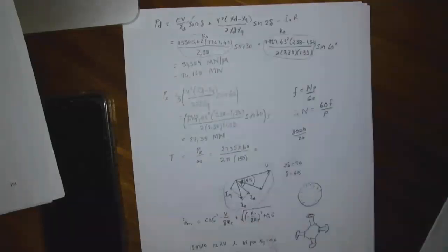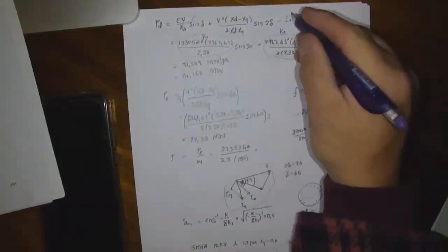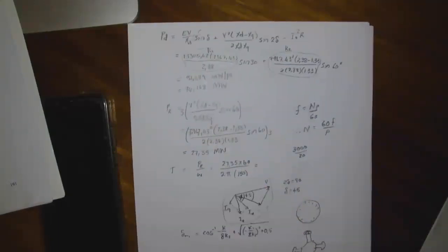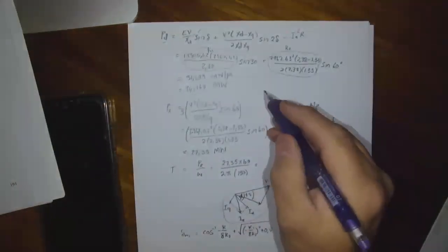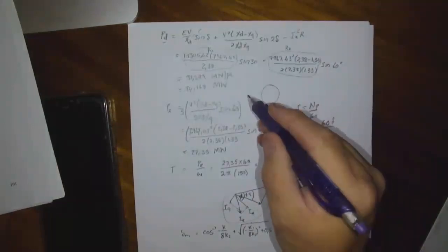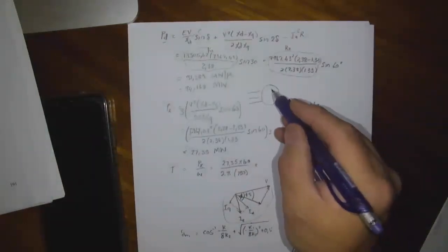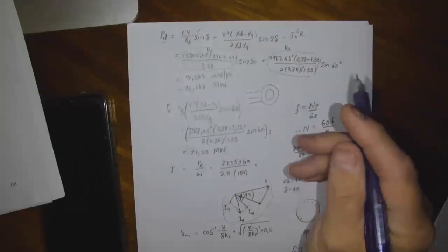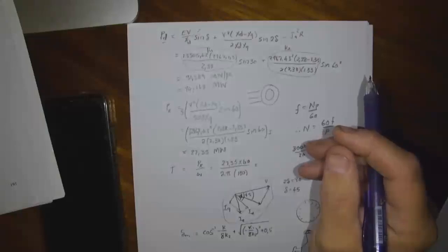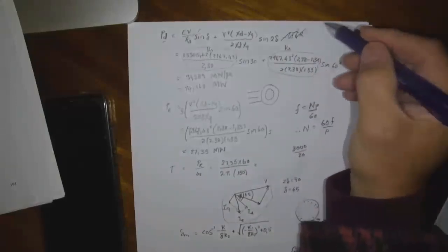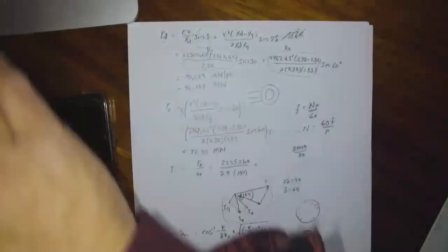Now you're going to subtract it. No, remember for a motor it's the other way around. This developed power is going to be inside of your stator. I think you just leave it out, just like that. And then when you calculate the output power, you subtract I squared R. All right, sir.